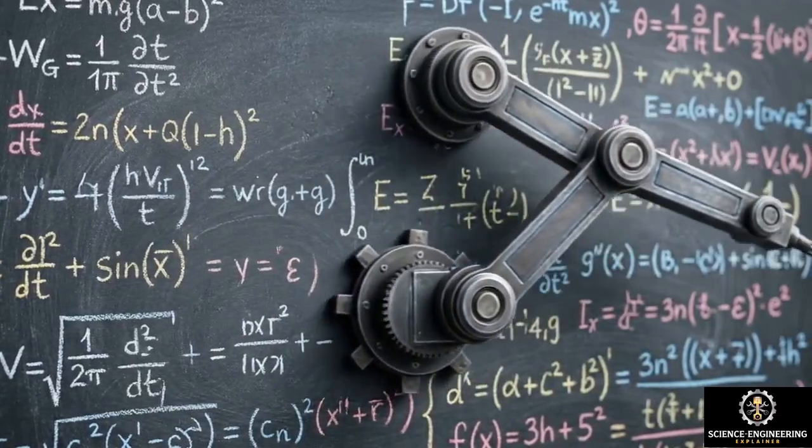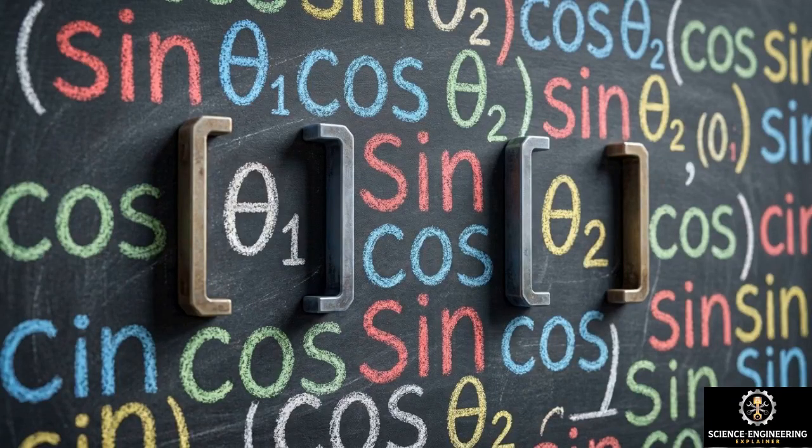This extraction process fundamentally maps the physical arm to a complex system of 3 nonlinear equations with 3 unknown variables. The x and y equations are highly coupled. Unknown joint angles are trapped inside identical sine and cosine functions, making them impossible to solve independently.